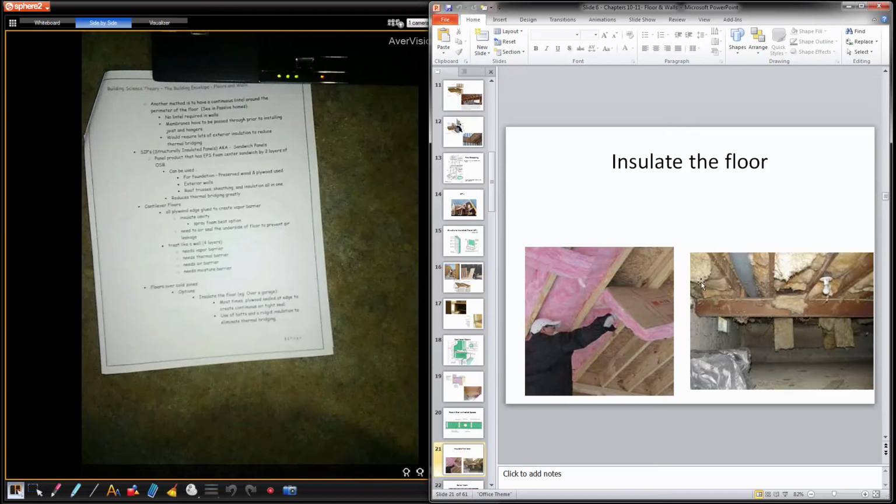So at bare minimum, what they should have done is put strapping probably every 2 feet to stop the insulation from falling down. I would put tar paper first and then strap it. That would have been bare minimum. Tar paper on the underside of a crawl space is not a bad idea because it's acting as a moisture barrier. Maybe the plywood floor, if glued, is acting as vapor and air barrier. Right? So you're not having to worry about putting membrane on the underside and sealing it around everything. You're just trying to stop moisture from getting in.